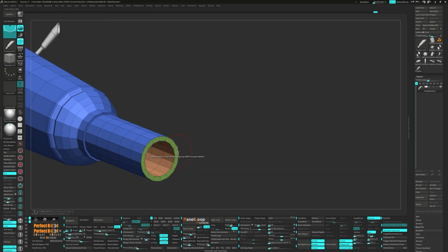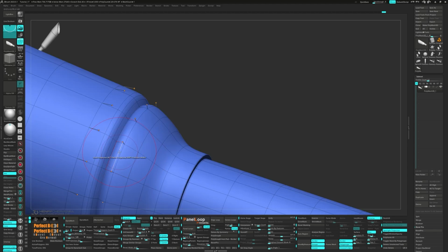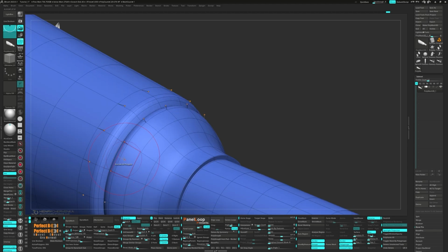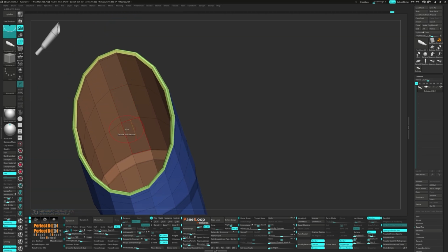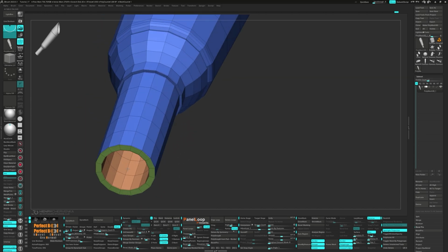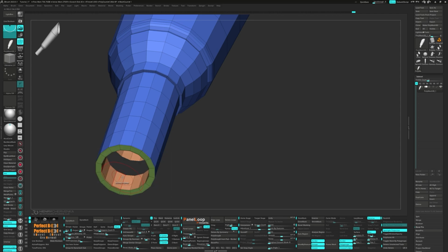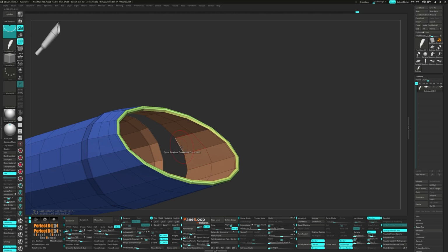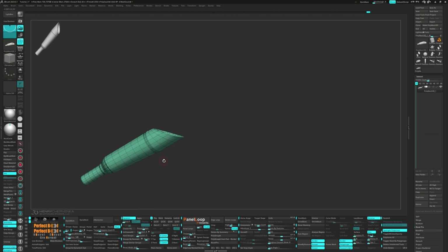Turn on dynamic, set the smooth subdivisions to 4 and the crease level to 3. Now we want to delete the 2 internal poly loops. Next, crease the edge loops. Then delete the island. Finally, group visible with Ctrl W and then turn on dynamic.